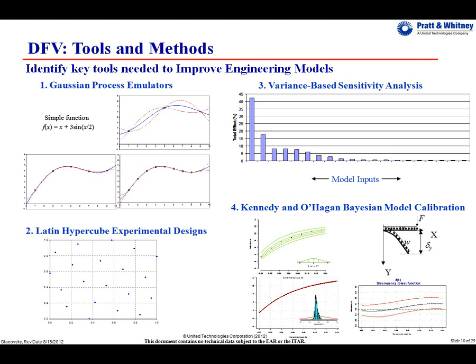They were not getting any understanding of interactions between inputs, and they weren't always getting a full sensitivity analysis of all the inputs that they really should be looking at in their models, just maybe what they felt were the top 3 or 4. Test those at a low or high level and see what comes out of it. In the best cases, they were running a factorial design and then analyzing the results there. But even then, they usually weren't covering all the inputs.